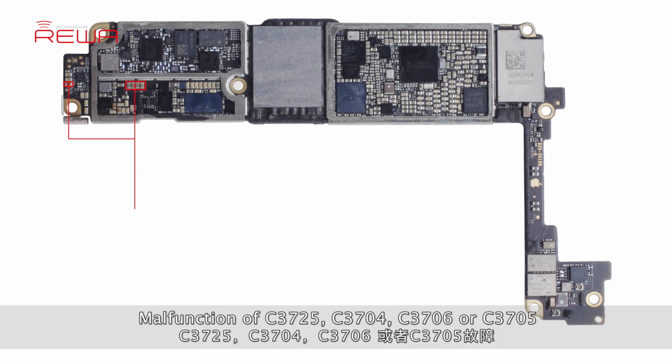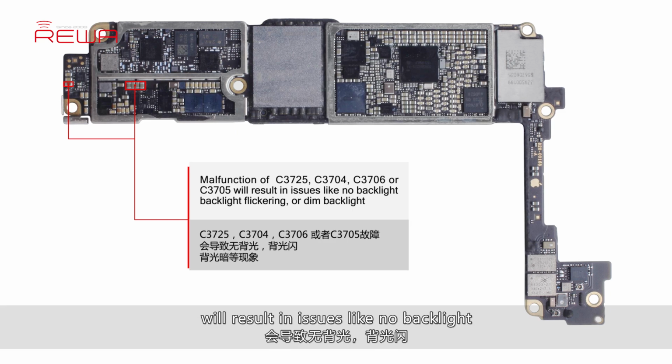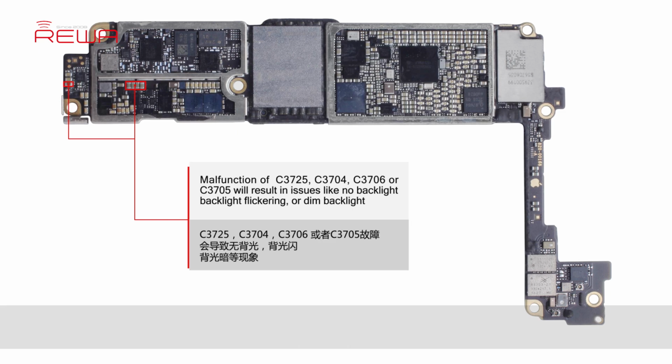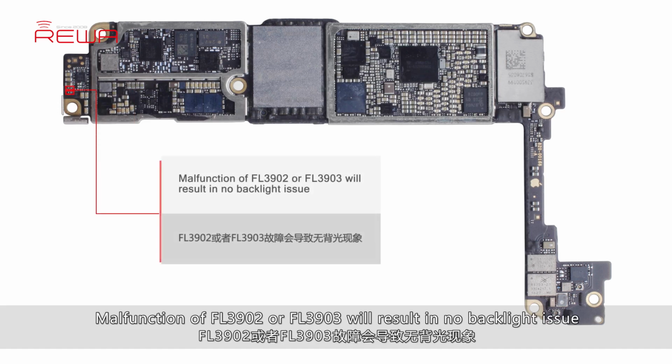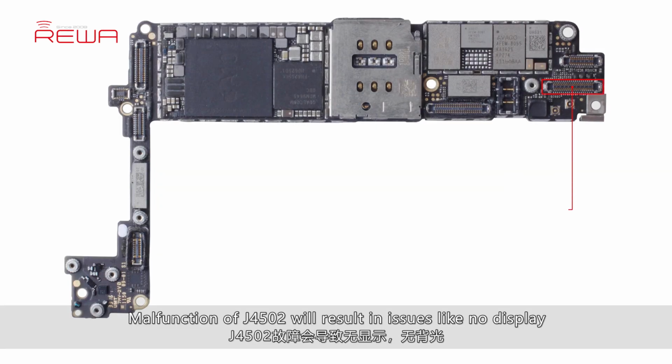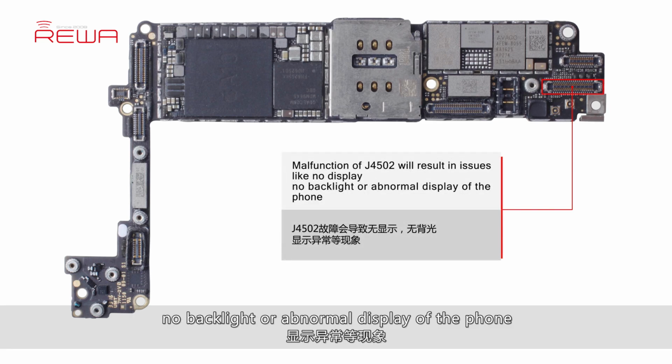Malfunction of C3725, C3704, C3706 or C3705 will result in issues like no backlight, backlight flickering, or dim backlight. Malfunction of FL3902 or FL3903 will result in no backlight issue. Malfunction of J4502 will result in issues like no display, no backlight or abnormal display of the phone.